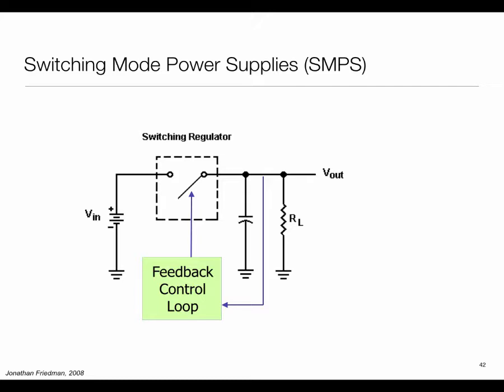And then I smooth it out through the circuitry. So effectively, I'll get 2.5 volt. The fraction of time this guy is on controls what voltage is being seen out here. Those of you who are EE would have seen this stuff. The main point is that I have usually a little processor sitting out here, monitoring the voltage being delivered, comparing it against what I want, and controlling the fraction of time this switch is on.